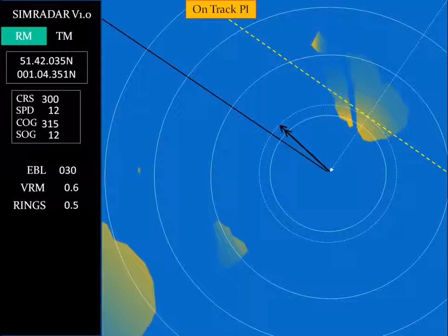However, knowing you are off track doesn't help in knowing how much safe water you have. In fact, the main purpose of PIs is not to tell you that you are on track, but to provide an instant indication of safety in relation to the available navigable water. This is done by creating no less than and no more than PIs to enclose the ship's track on both sides.